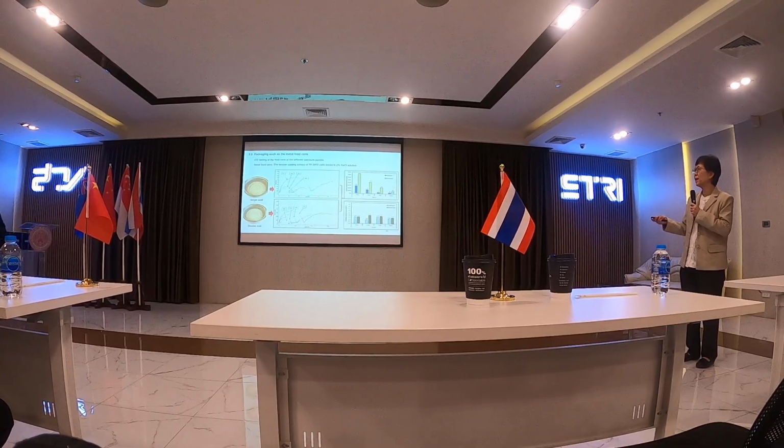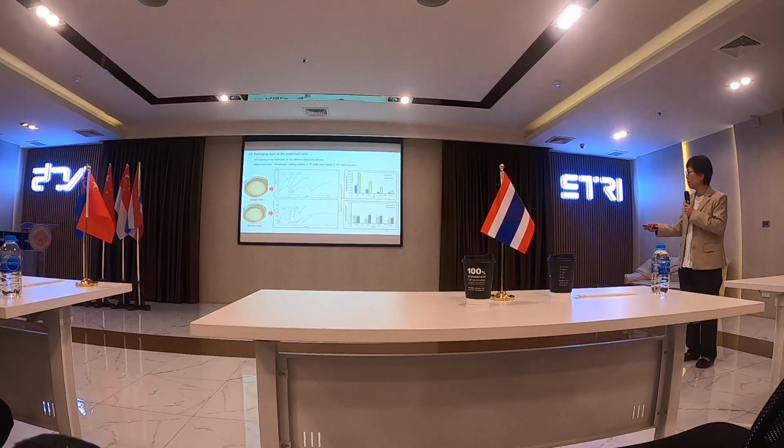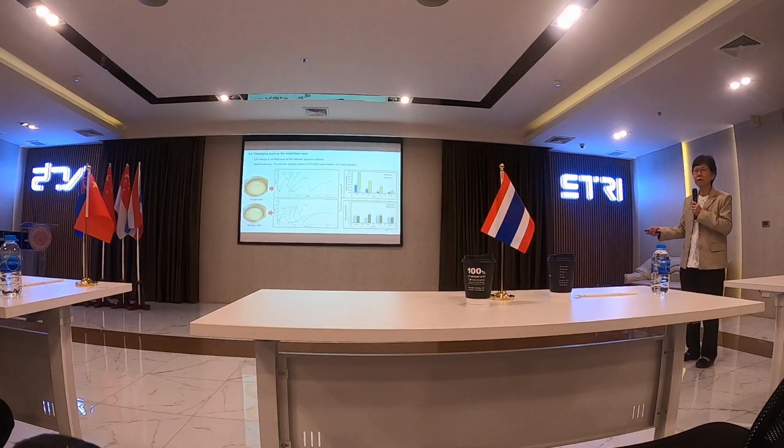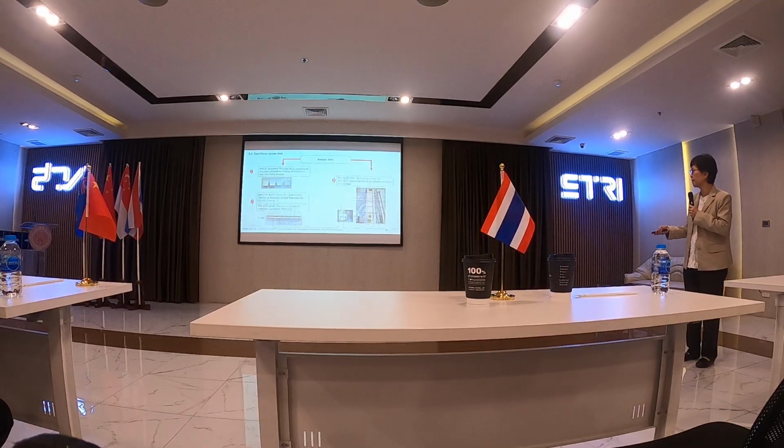This we use for packaging. We study the packaging and we do a shelf life study for the company. So we use tin free steel with draw and redraw cans in sodium chloride solution, and then we do EIS. We measure the resistance of the lacquer as well as the water uptake of the lacquer.